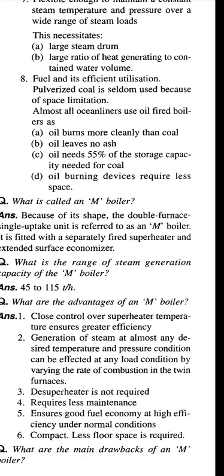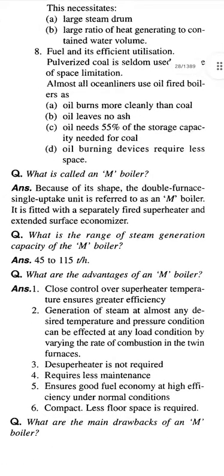Eighth one is fuel and its efficient utilization. Pulverized coal is seldom used because of space limitations. Almost all ocean liners use oil-fired boilers as oil burns more cleanly than coal. Oil leaves no ash. Oil needs 55% of the storage capacity needed for coal. Oil burning devices require less space.